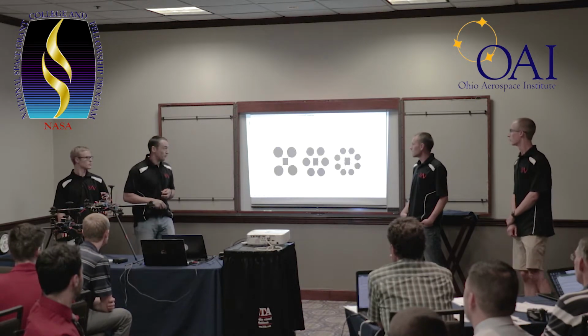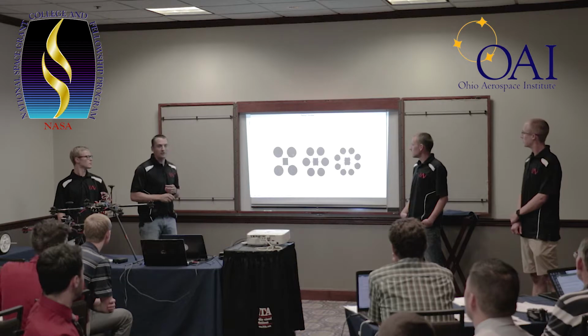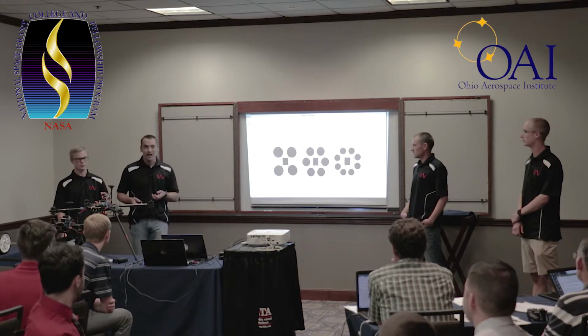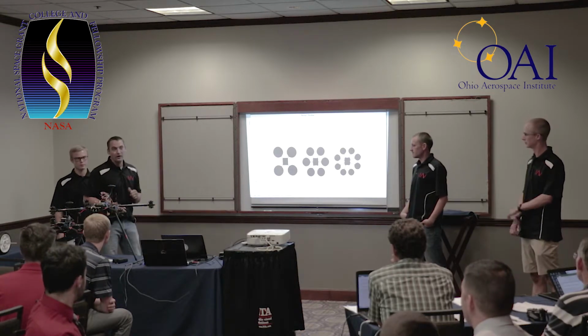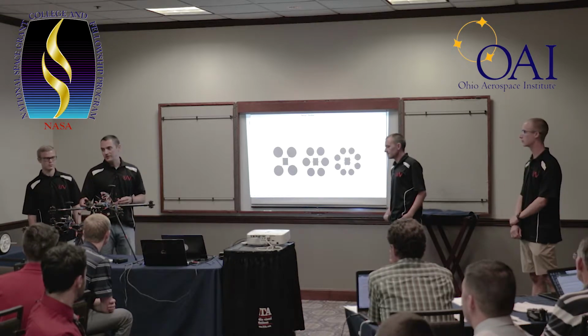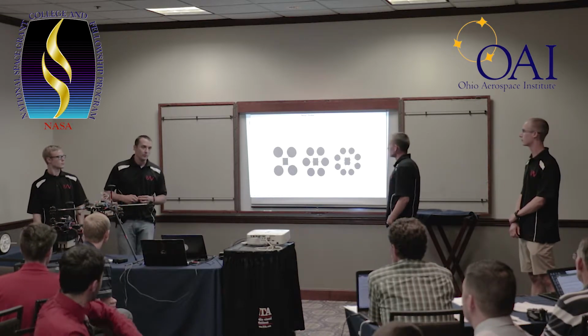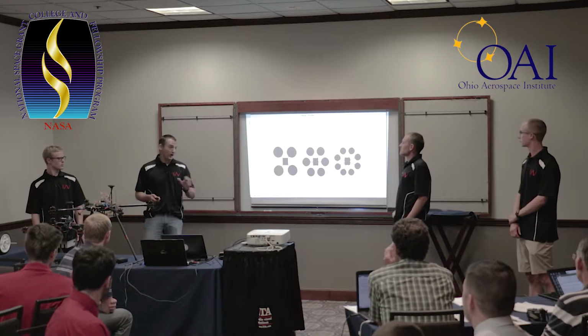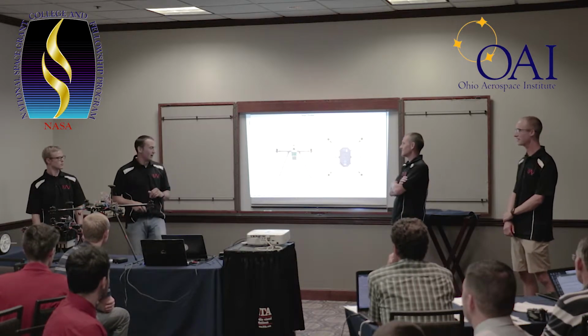So what that goes to show is that the fault tolerance involved in a stacked coax is actually really good, considering the thrust efficiencies of the top and bottom motor. So we really proved a fault tolerance, even though we weren't out to prove a fault tolerance whatsoever.